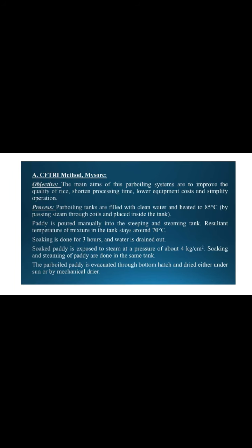The CFTRI method was developed at the Central Food Technological Research Institute, Mysore. The main aims of these parboiling systems are to improve the quality of rice, shorten processing time, lower equipment cost, and simplify operations. The process: the parboiling tanks are filled with clean water and heated to 85 degrees Celsius by passing steam through the coils placed inside the tank.